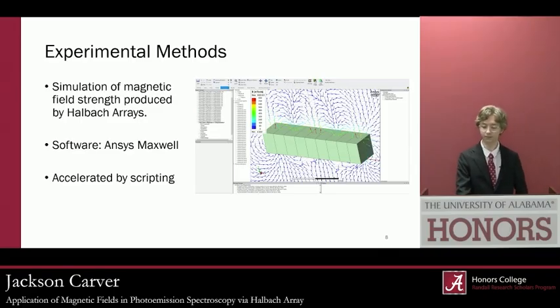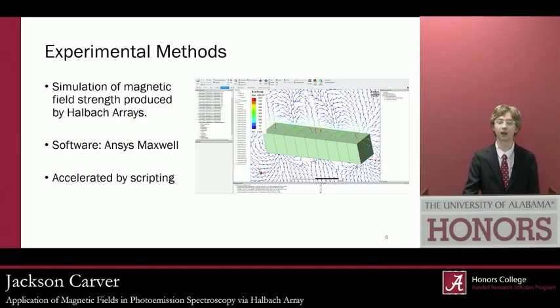We wanted to test the effect of several parameters on the magnetic field, and thankfully, Maxwell allows for scripting. With this feature, we could create a general array creation script, allowing us to make and simulate arrays of different parameters automatically rather than manually.